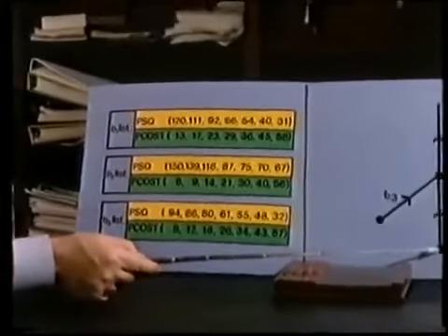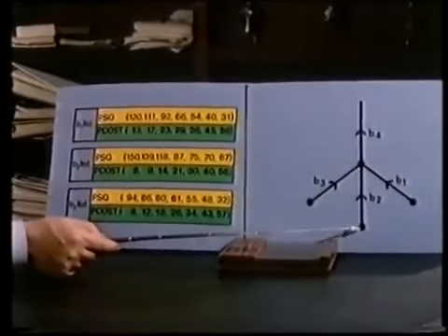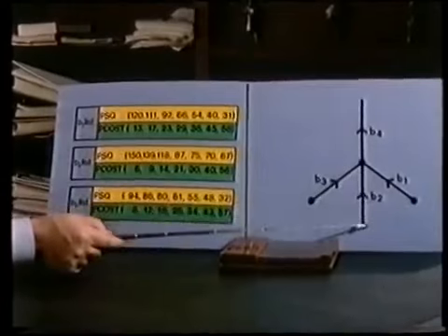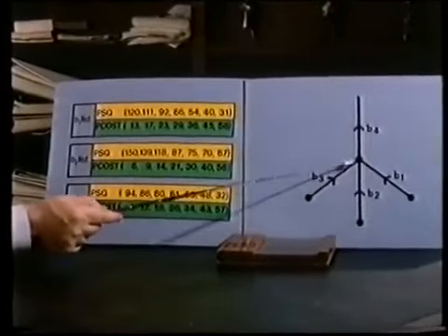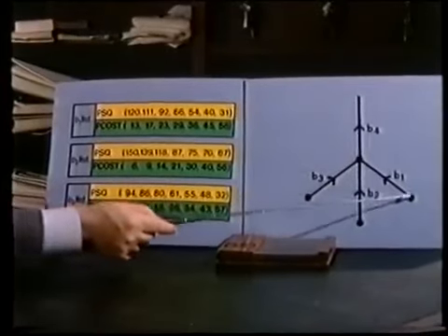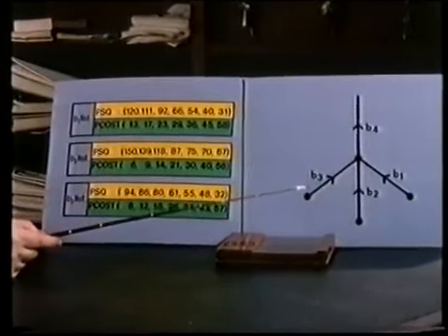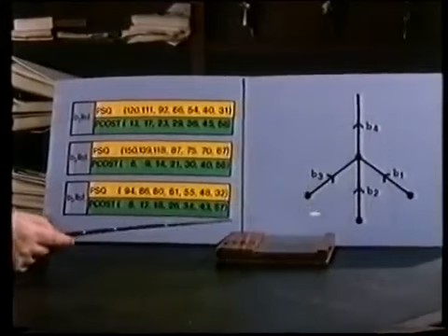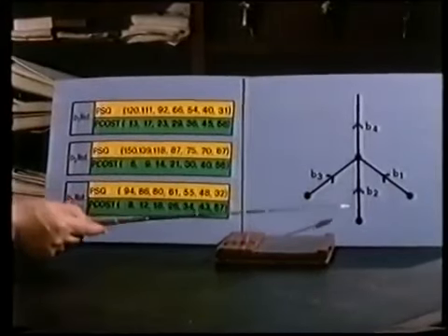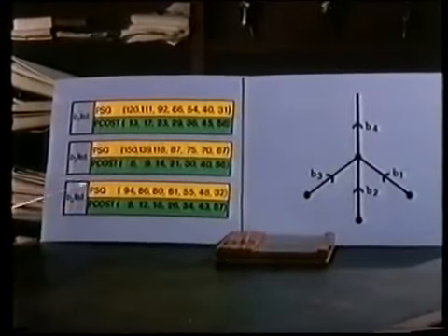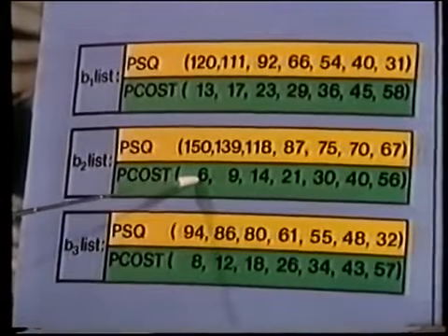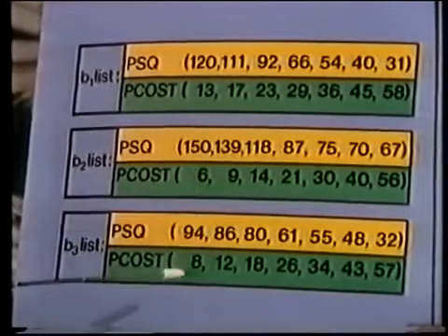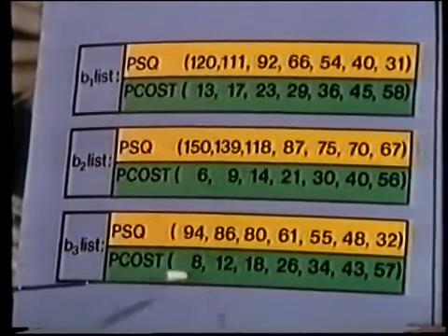And the important point to notice is that I can immediately conclude that if pipe B2 has the smallest possible diameter, then I never need to have anything other than the smallest possible diameter on pipes B1 and B3. I can't relieve the critical pressure point, and I can only spend more money. What I've then done is I've eliminated having to examine those possible diameter combinations.